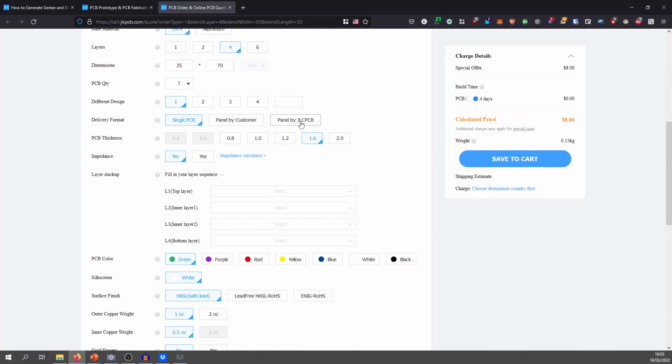If they're in a panel, you can use your, what are they called? The template. Yeah, the stencil, to solder them up. So you've got a big metal stencil, put some solder paste over it with a squeegee, and take the stencil off, and then you can just place all the components on a big panel. Rather than doing tiny little boards at a time, it would take a long time. Good for a bed of nails sort of test rig. Yes, exactly.